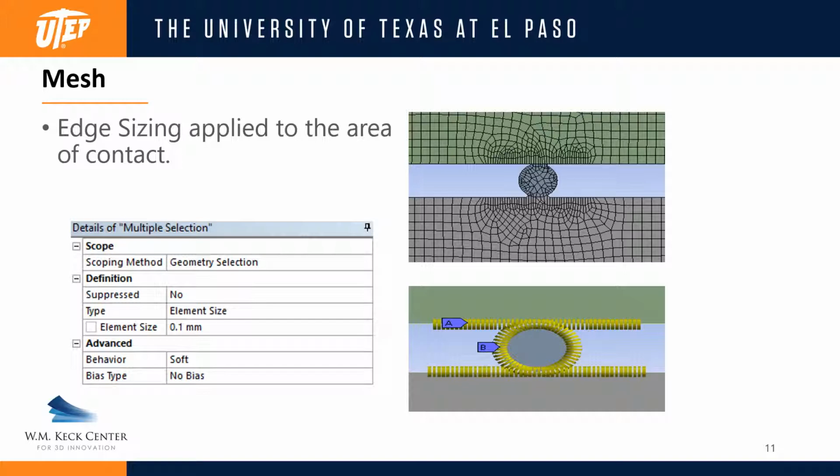On this one, I used an element size of 0.1 millimeters, and this gave me a total of 17,969 nodes and 5,802 elements. The limitation on the student's license is 32,000, so I was below, but if I added a bunch more fine meshes, it would be a limitation on my simulation.